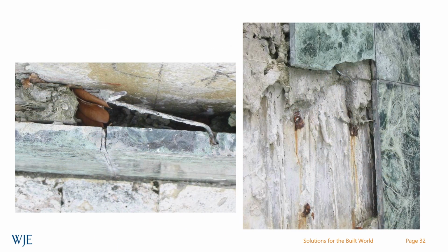Much of the detailing of thin stone applications in this particular image, serpentine, was that stone detailing that had been used for the interior of buildings was used on the outside of buildings, and that was not generally a good idea because of the significantly higher loads and exposure that the stone was subjected to during those time periods. But that was a detail and detailing system that had existed for a number of years at that point. It just hadn't been moved to the outside in thinner stone application.